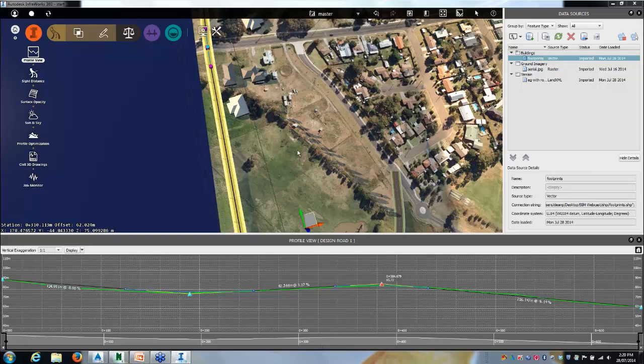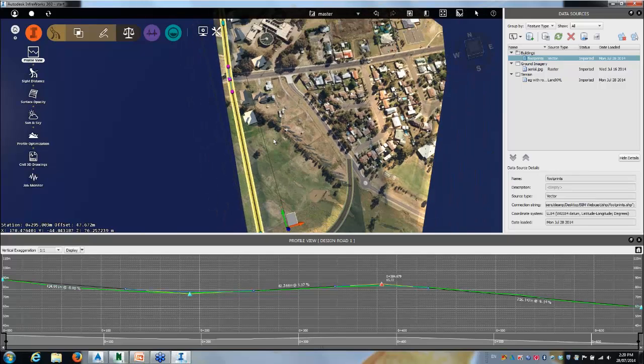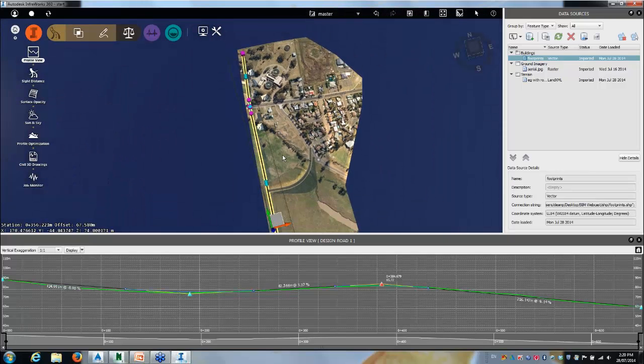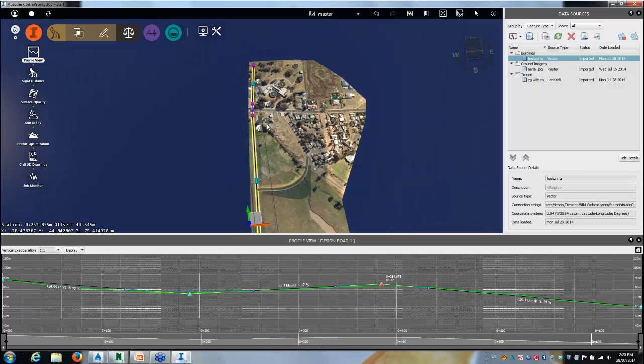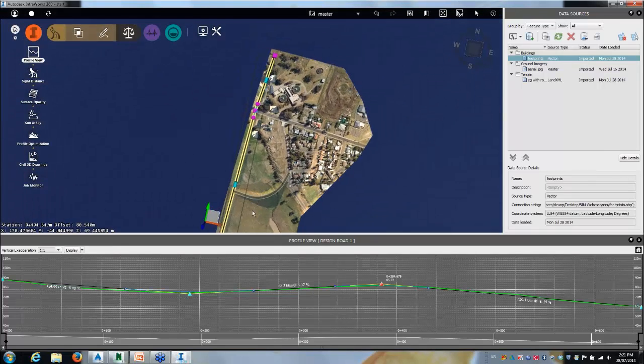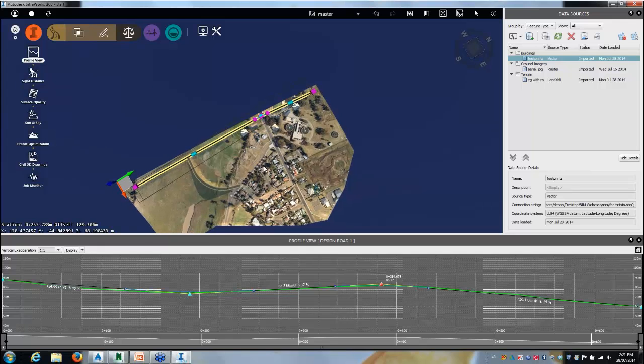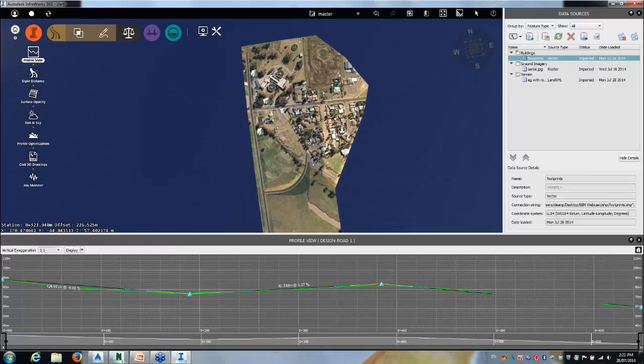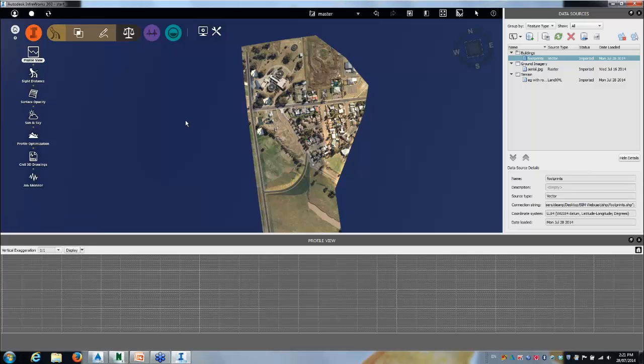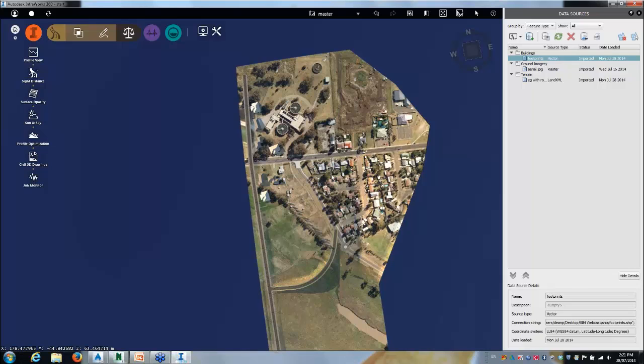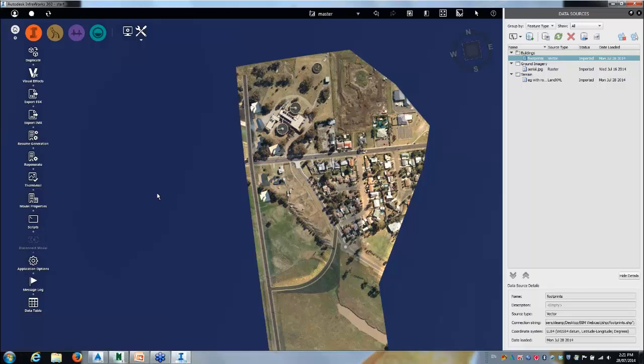So quickly, we've got something started in InfraWorks, and we want to now transfer that to the next program. So the best way to do that is, the next program being Civil 3D. Let me close this thing here. So we want to make an IMX format, which is a file type made almost specifically for InfraWorks and Civil 3D.